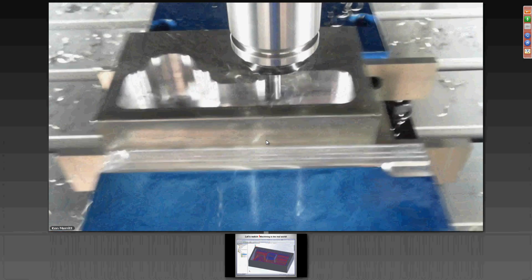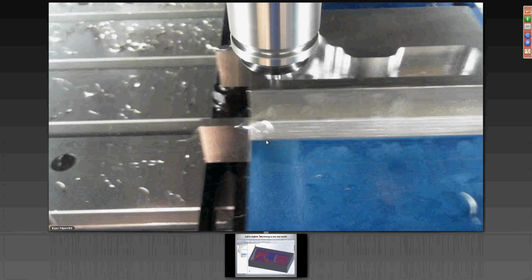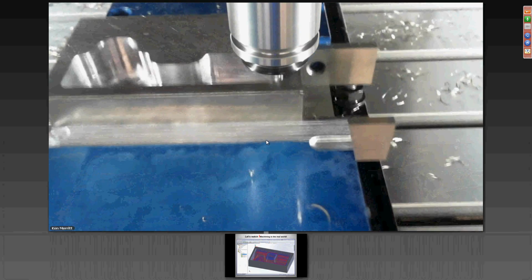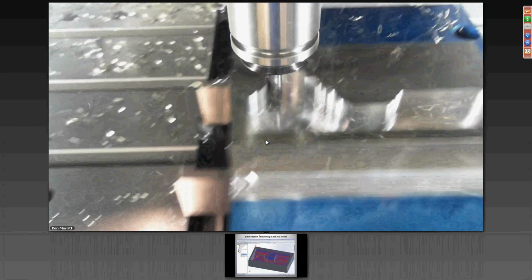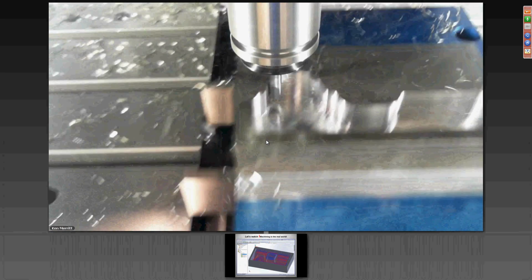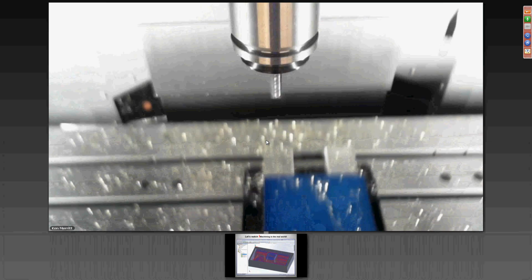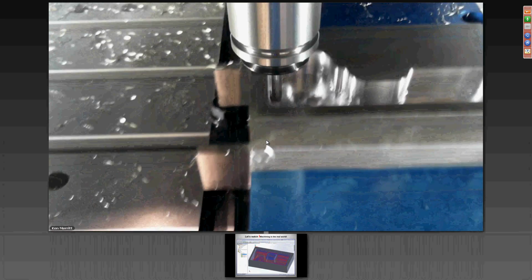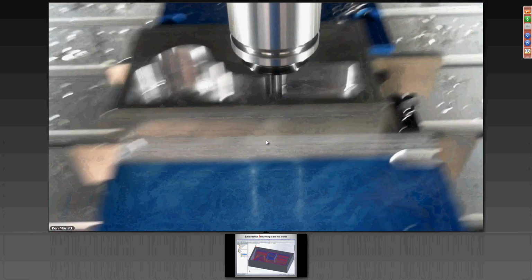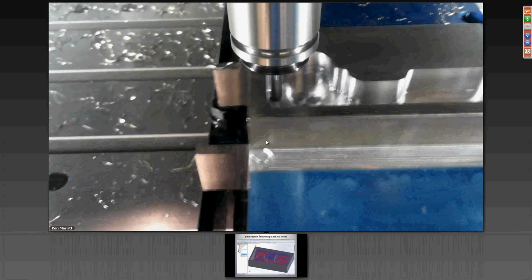Also notice that the reposition move you just saw was down inside the pocket. One of the things that we've put an extensive amount of effort into is optimizing the repositioning moves. With our 3D iMachining, every movement of the tool is also updating the remaining stock qualification. So we have this constant stock update, and for each movement of the tool, during runtime of the algorithm, we're recomputing where that remaining stock is so that we know exactly where we can safely move the tool. That way we don't necessarily have to return to the rapid clearance plane all the time, which can be a bit of a hindrance.